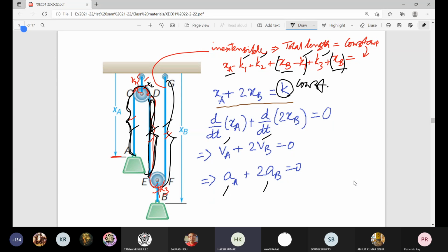So Sir, there is another method, no? By pulley method, we can do like velocity of pulley is equal to V1 plus V2 by 2, where V1 and V2 are the velocities in the component strings. Okay, these are the formula. And whenever you are talking about the spring, then naturally we are talking about the force developed in the spring due to compression or tension. But including that item force, it is coming under kinetics. For the time being, we are keeping it apart. Only the geometrical relation. The geometrical relation is that the total length is constant.